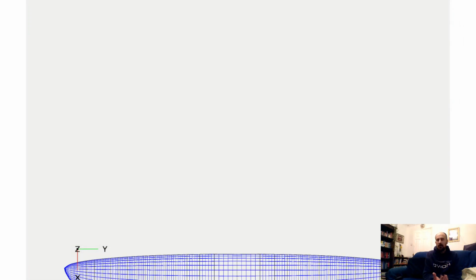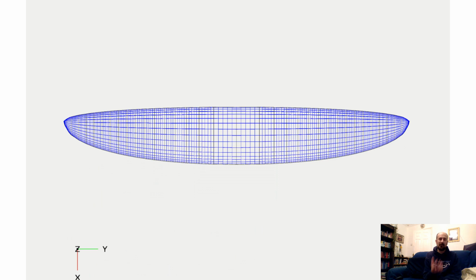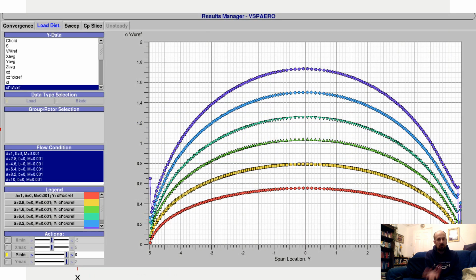and we've obviously got an awful lot better since then, but we're still a massive long way off having an optimal lift distribution. So bearing in mind that the elliptical planform wing gave an elliptical lift distribution across all the angles of attack, let's have a look at how a hang glider wing does now.